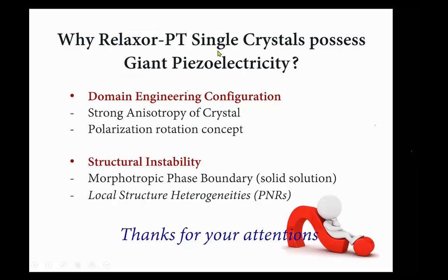Why does a relaxor-PT single crystal possess giant piezoelectricity? It is attributed to the domain engineering configuration, taking advantage of the strong anisotropy of the crystal and the polarization rotation concept. It is also attributed to the very important structural instability. The structural instability can be induced by the morphotropic phase boundary, and also most importantly, it can be induced by the local structural heterogeneities, that means the PNR.